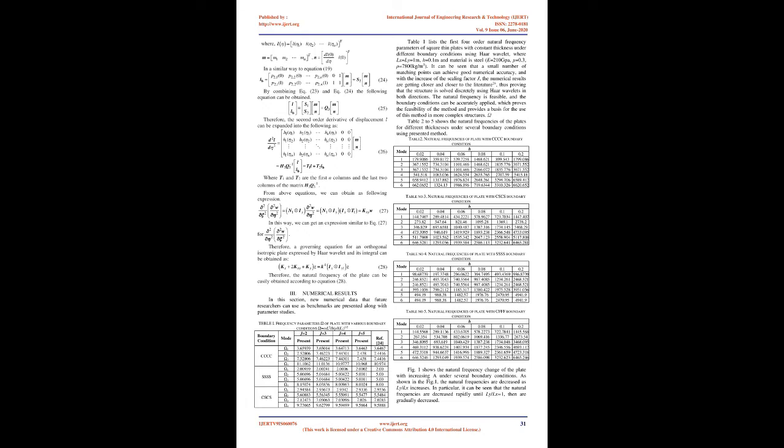By integrating equation 4, the following derivative terms can be obtained. The displacement function can be written in the form of a matrix as follows. In practical applications, the clamped boundary condition, the simply supported boundary condition and the free boundary condition are widely used. These boundary conditions can be written as follows in equation form. Clamped boundary condition: 4 boundary condition equations can be obtained by introducing the boundary condition, and can be written as